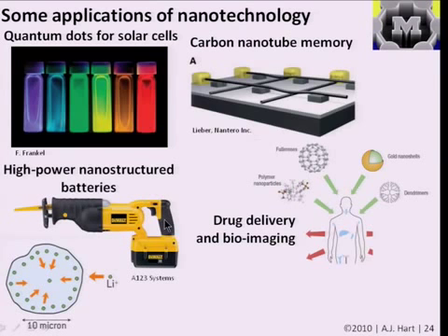Another example that is on the market today is the use of nanostructured materials in battery electrodes. And this company came out of a lab at MIT, and it's probably one of the examples of the fastest moving nanotechnology companies to date. What they realized is that a battery electrode is designed to store electrochemical energy, for example, to shove lithium into a solid material, and then that's your stored charge. When you want to power something like a power tool, you let that lithium out of your electrode and a current is generated because of the electron transfer that occurs when the lithium comes out of the material.